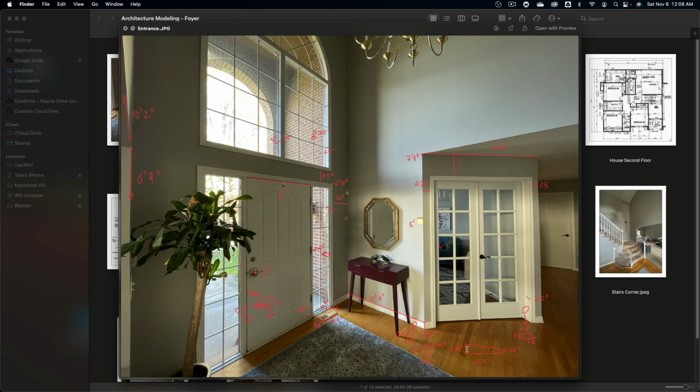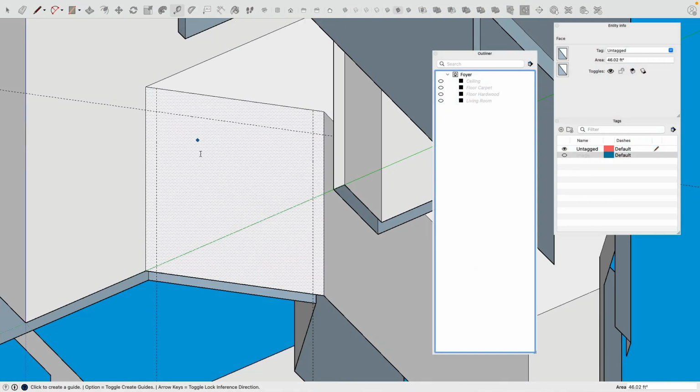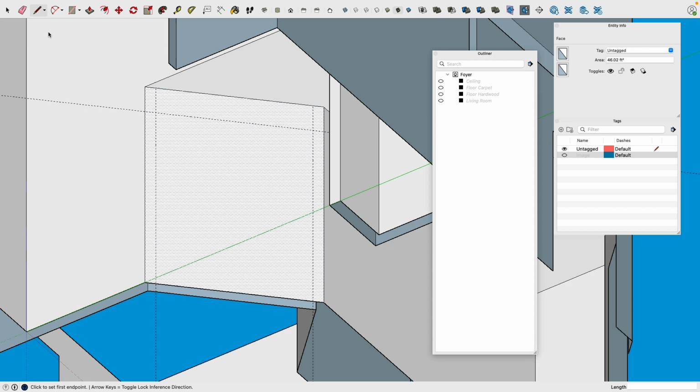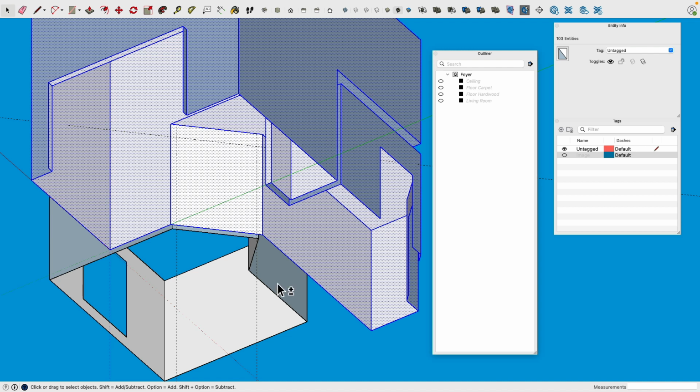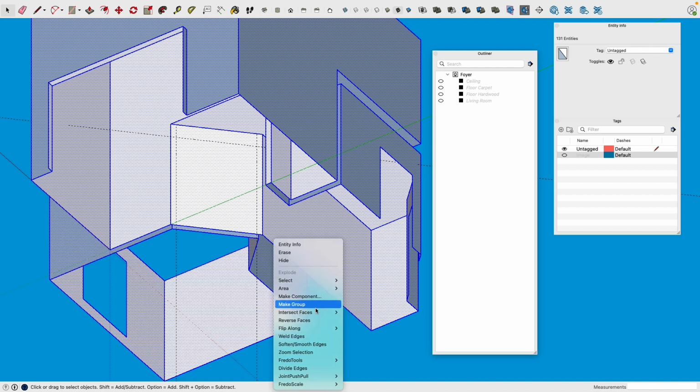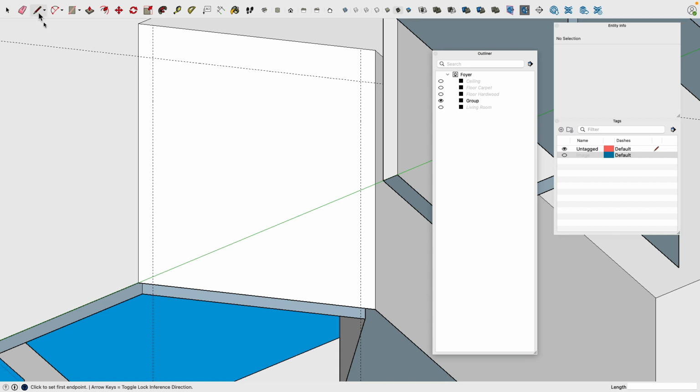Okay, so this shape I'm going to draw and then line it up along this line here, and then we will do a sweep. Good. So this is going to be my sweep path. There we are. But I'm starting to cut onto the walls. So you saw now this is not actually really good. So what I will do now is select everything and group it because I do not want this to be glued onto the wall.